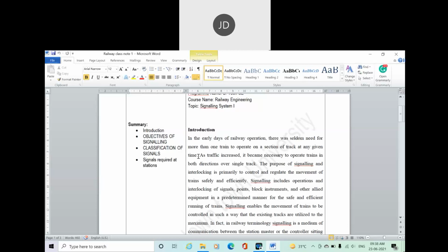This is an HW2000 points machine. This is electromechanical. What we have here is your drive motor. To check the motor has done its job, over here we have an interlocking and detection system. Detection tells us when the points have completed their travel and locked. Locking holds the points in this state so they cannot be physically moved, so when a train runs over the top, it remains in position.